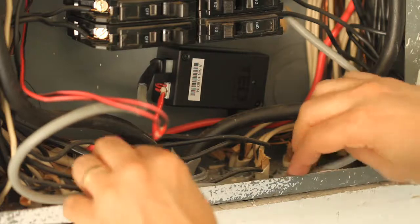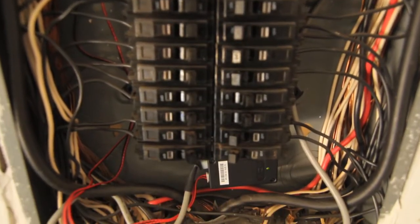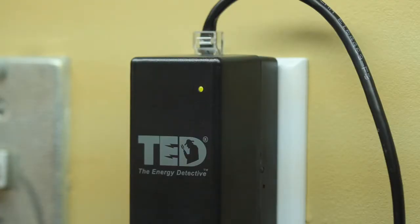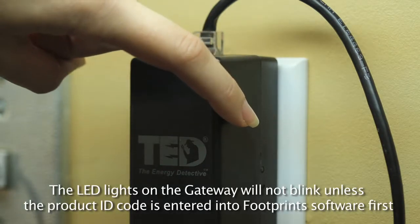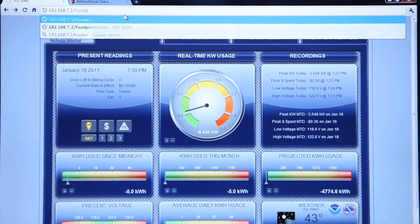Remember that the black wire needs to be on the same phase as the circuit going to the gateway, and note the change in the settings as explained in the video. Here's the best strategy to determine if filters are needed. Once the system is set up, observe the LED on the side of the gateway as described in the installation video. You will also want to use the gateway stats page.